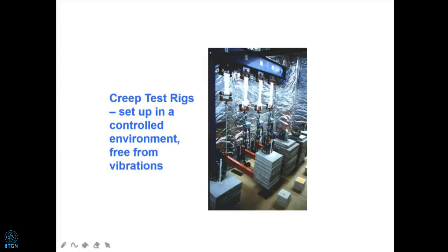We have the specimens here, and naturally we apply low load, higher load, much higher load, depending upon what we are trying to do. There's a lever arm here also. All of this is almost like consolidation tests, except that it is at a given temperature, mind you. The temperature is monitored continuously. It can't be plus or minus 2 degrees Celsius. It must also be free from vibrations. If there is external vibration in the structure, naturally the result is not accepted.